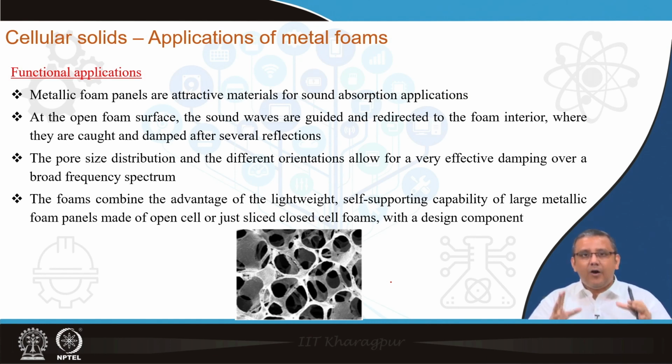What is the difference? Open cell foam contains only the cell edges. As you can see from this particular image over here, these are only the individual edges joined together. There is no material between the edges, and that means there is no face in this, that means the cell faces are missing. I gave this example at the very beginning: you can imagine the room in which you are sitting. If the walls are all missing and only the corner pillars are there, you can imagine yourself to be sitting in an open cell foam or an open cell room.